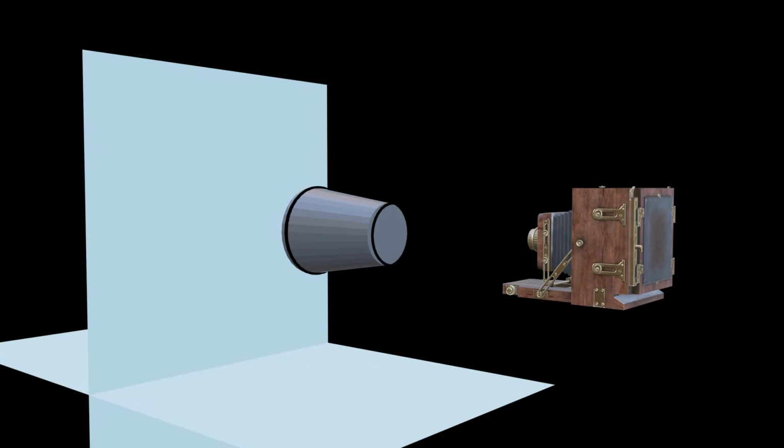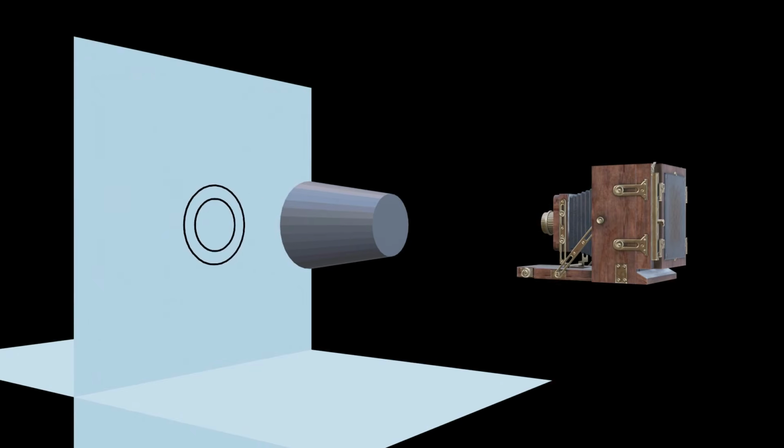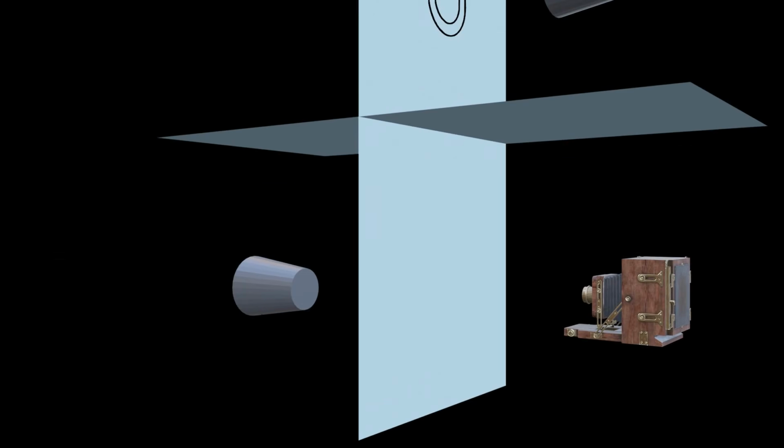We stand in front of the cone, so we take a picture of it. The view we see now is two concentric circles, and using the same analogy in first angle projection, you would throw this picture behind the part. In third angle projection, you would put this picture behind you.